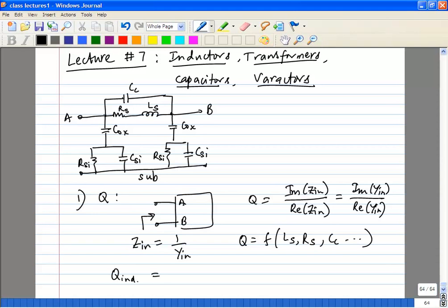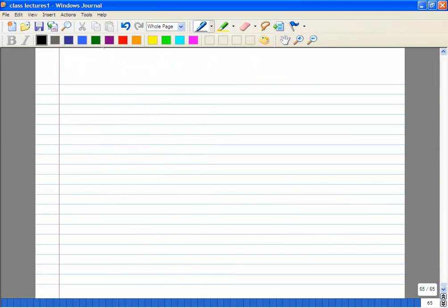But the other important thing to notice, if you use this definition, for example if you have some capacitance, we looked at it as omega L minus 1 over omega C, over R. You'll get some expression like this. You have some inductive effects and some capacitive effects over the resistive effects. This is valid only as far as the system is an inductor. Beyond that, the numerator will get negative. So when you plot it, you will see some negative Qs in your simulations, but you just have to keep this in mind. The Q definition is no longer valid beyond that. Now the other thing we looked at is the self-resonant frequency.